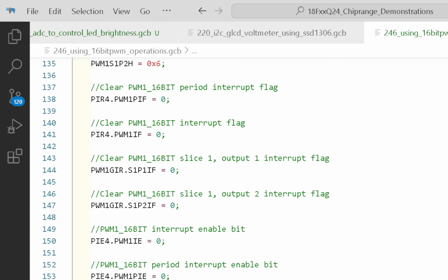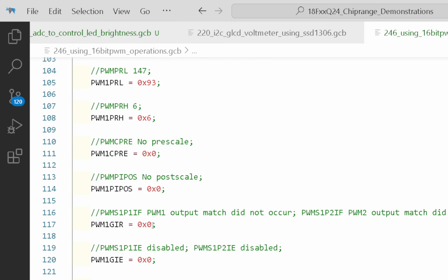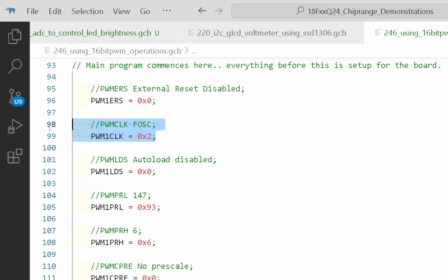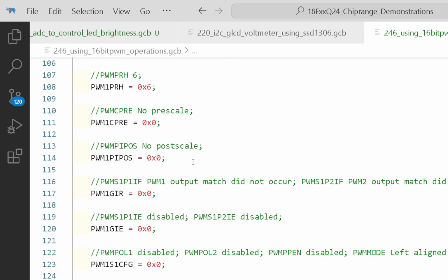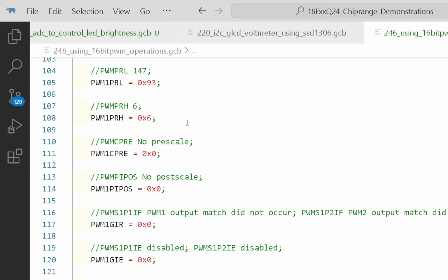and then at the bottom, I then enable it. So what I've done, if you can think about it, in PPS, I've enabled the modules. Yep, I've said attach yourselves to the LED ports. I've said, right, my clock source is in actual fact the frequency of the main oscillator. No prescaler, so whatever numbers I'm going to give you now, don't be mucking around with them, just live with it. Then I've said I want to use a specific frequency, and I've said that here.